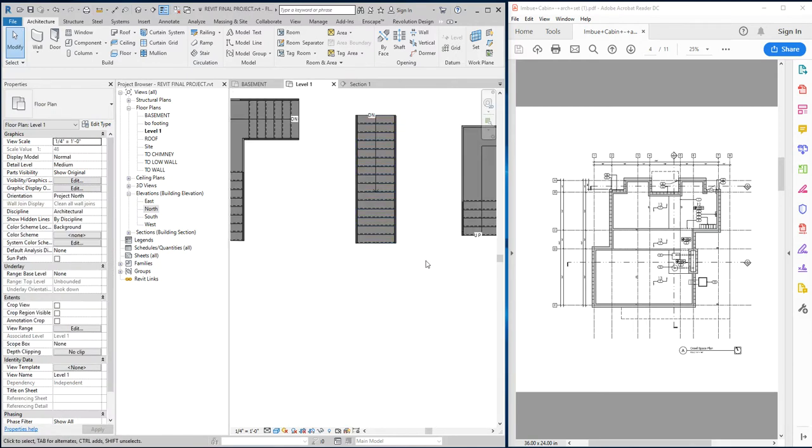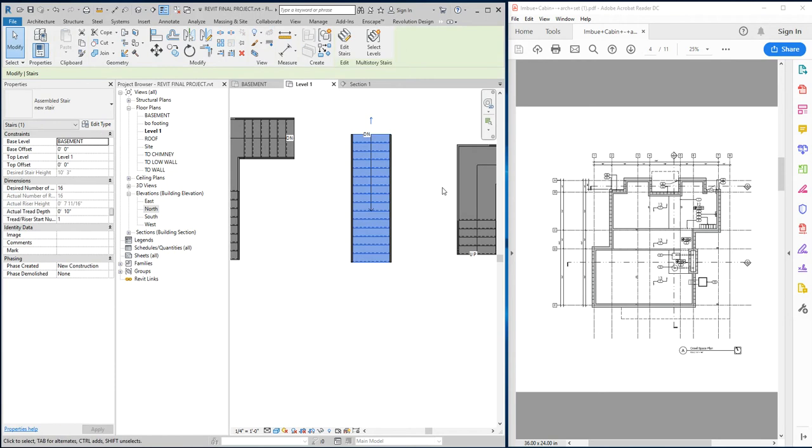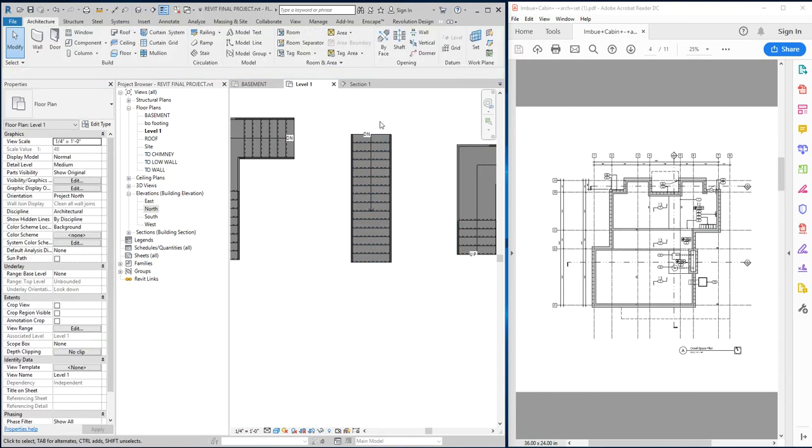Which in AutoCAD would be heartbreaking. But in Revit, what's nice about stairs is that when they're finished and I select them, I get this little grip right here. And if I click it, it just flips the orientation of the stair. So even if I get it drawn completely backwards so that it's going up when it should go down, I can click that little reorient grip, and I can make it correct, right? It's always the right shape, for me at least. It just goes in the wrong direction for whatever reason. There's got to be some drawing methodology. And like I said, I've experimented. I need to look up the formal way.